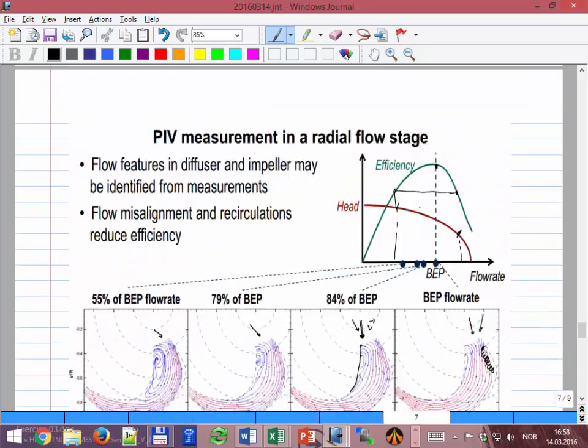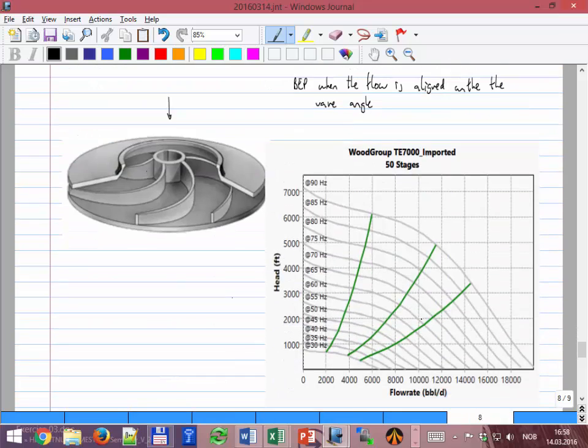So one thing that now maybe you can tell me, the points that we said was something like this, right? Going up, and then going to the left. What do I have to do operationally in the pump with time? Change the frequency. I have to increase the frequency all the time, just like opening the choke all the time. In this case, I have to increase the frequency up until it reaches a point where I again have to reduce it.